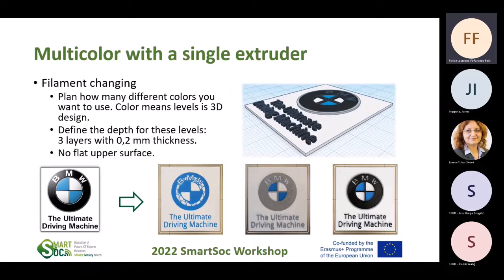For example, in the case of this cup, it's trivial that the bottom part of this handle needed a support structure, because you can see that the lowest point otherwise would start in the air. So definitely here there was some structure. But you don't have to plan it in advance because the slicer program will generate it according to your settings.